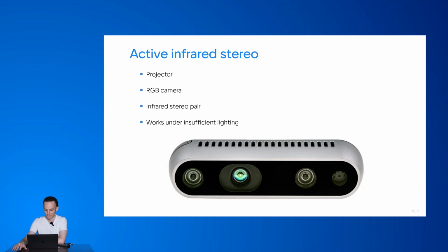One thing that is better in Intel RealSense, in contrast to passive stereo, is that it works in the dark. While you're trying to distinguish, let's say, dark blue from dark green in HSV color space, or trying to find some black cat in a dark room, this camera will allow you to detect all the shapes and distances to the object.